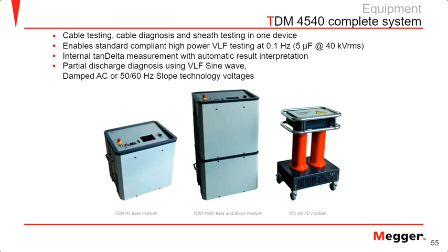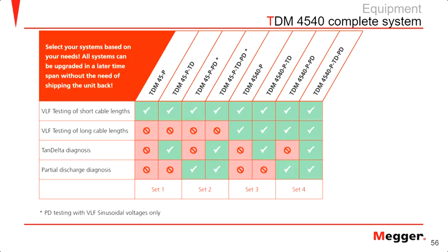If you want a more complete solution, then we have VLF along with the partial discharge, and it provides CR and DAC waves as well to interpret partial discharges. So this is a complete setup. This is also very customizable. If you look at all the different options, you can pick and choose based on what you do and what you don't do. So it is a more customizable solution.